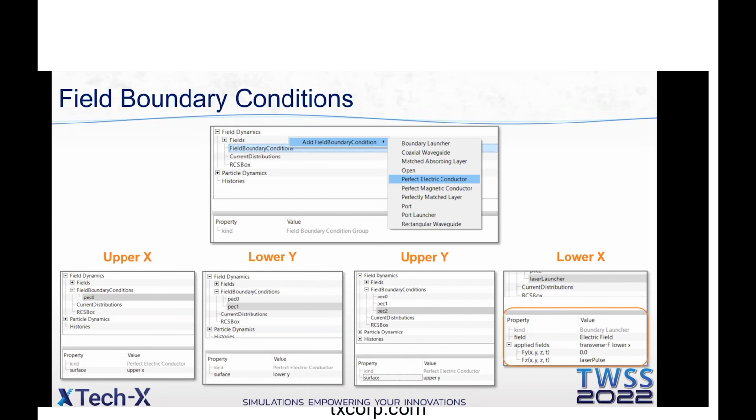So you've got to figure out what's the best approach to modeling your physical system. If your plasma or whatever it is really inside of some sort of metal can, then you want to have perfectly conducting boundary conditions. Those are your best approach to the metal. But if instead you had some sort of incoming wave coming in through a waveguide, then you might want to launch it with a port, which would mean that if the wave hits whatever's inside the cavity or some structure and reflects, that reflection just cleanly leaves the simulation and doesn't come back into it, and thereby doesn't confuse your answers.